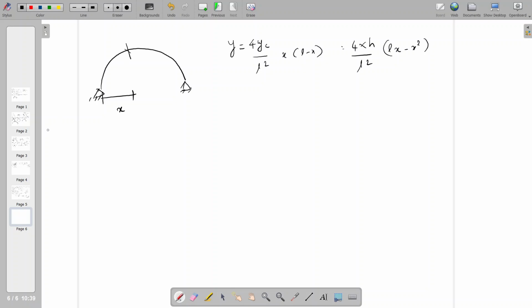So I am going to write the bending moment at this section xx. Mx equal to, we are having VA and H and the loading up to the section xx, that is W per meter. So Mx equal to VA into x, it is rotating in this direction, minus H into y.